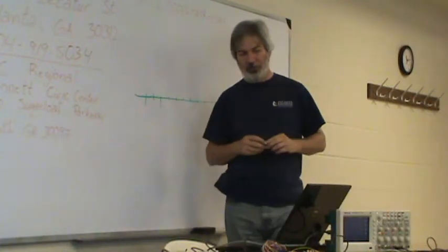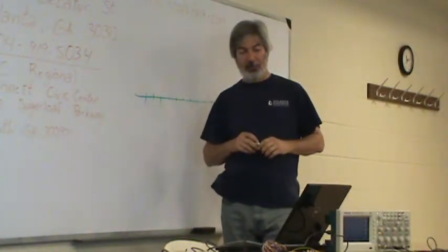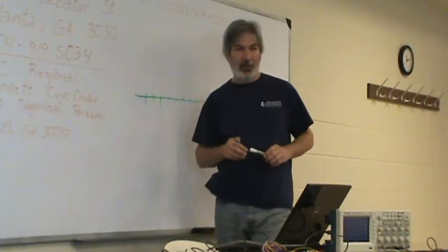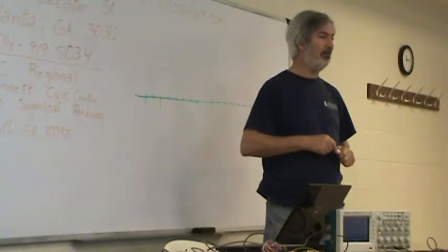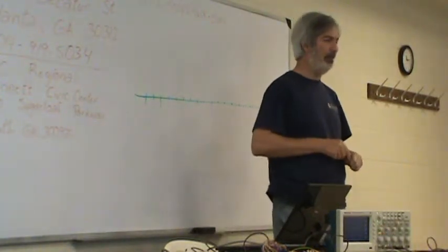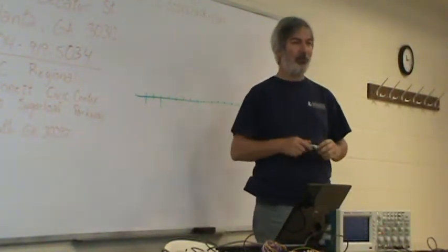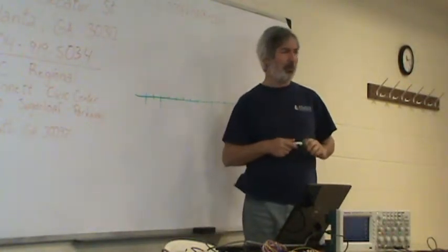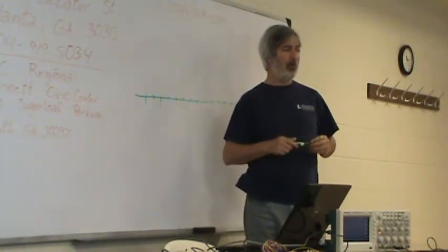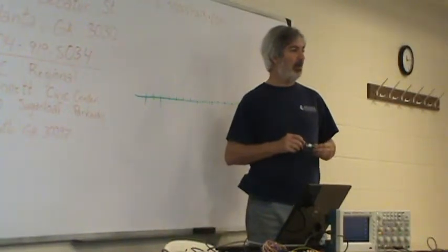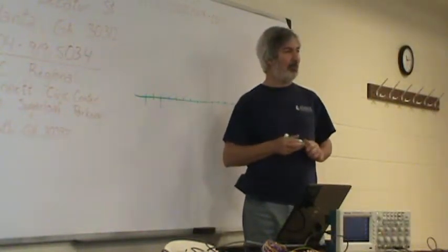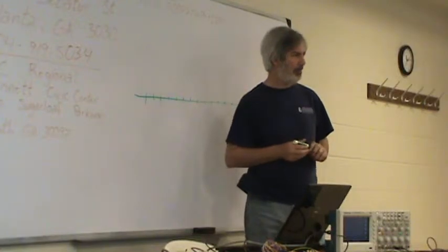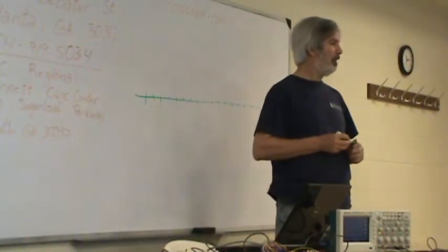And so what you'll do is attach your leads and take a look. Very simple. And usually you'll find out in pretty much a heartbeat whether you've got signal. Typically what I'll do is, when I'm hooking something up, such as a serial connection, before I actually hook the wires, I'll go ahead and scope out both transmit and receive pins to make sure that I really didn't get my, shall we say, my wires crossed. It happens all too often.